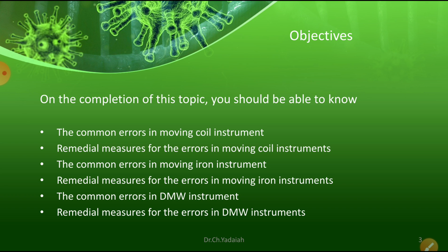At the same time, due to aging, the spring tension and stress also change. If the temperature changes, the tension or stress in the spring also changes. If the spring changes, the controlling torque value changes, which is opposite to the deflecting torque. Thereby, the error may occur while working.